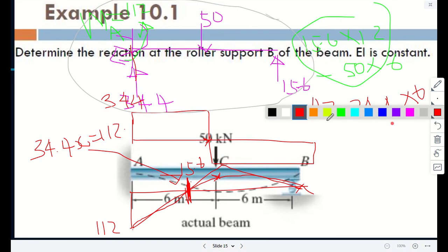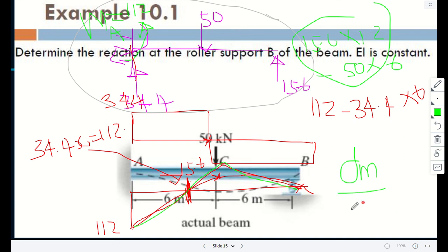So just to recap, if the shear force diagram is constant, then the bending moment diagram is linear. If the shear force diagram is linear, the bending moment diagram is a curve. This goes to the principle of dM/dx. If you differentiate the moment with x, you get the shear force diagram. That's why we have that kind of relationship.